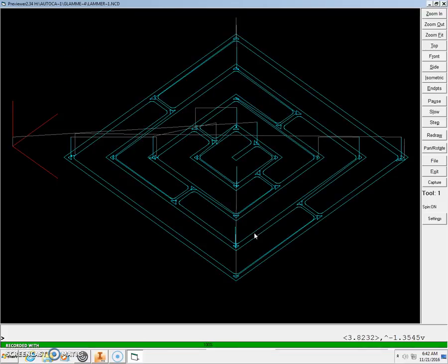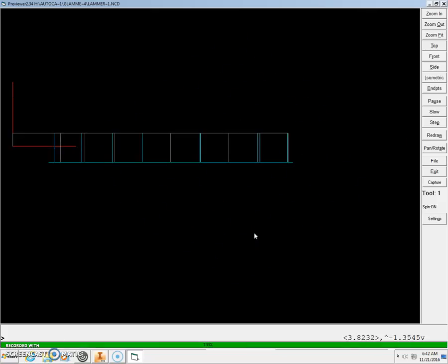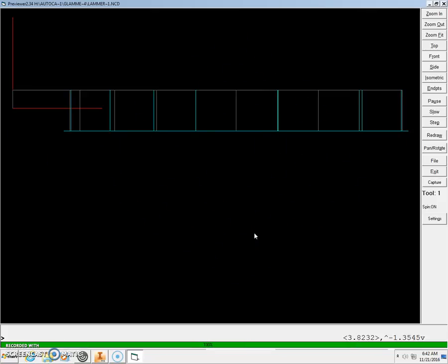Next, you're going to take and press S on the keyboard and F on the keyboard, and this is where you're going to stop. Go get your teacher. They will help you load the workpiece, and you're going to be able to cut your part today. Great job. Go find your teacher and have them come and help you load the workpiece.